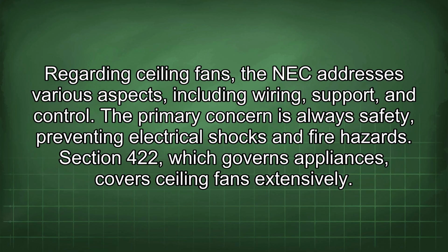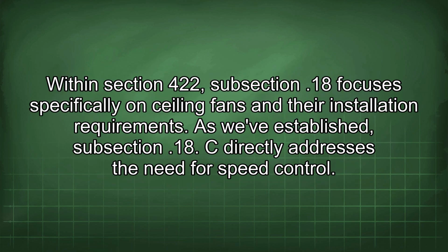Regarding ceiling fans, the NEC addresses various aspects, including wiring, support, and control. The primary concern is always safety, preventing electrical shocks and fire hazards. Section 422, which governs appliances, covers ceiling fans extensively. Within Section 422, subsection 18 focuses specifically on ceiling fans and their installation requirements. As we've established, subsection 18 C directly addresses the need for speed control.